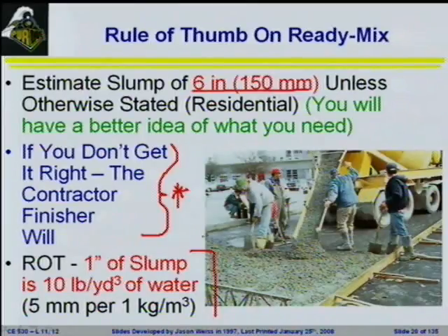And the other thing I will say is that I do not advocate using the rodeo sign when the truck shows up on site. Before someone leaves here and writes down, Professor Weiss said use the rodeo sign whenever a truck shows up: you are not to add water on site.